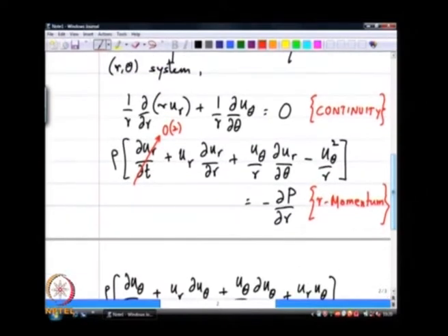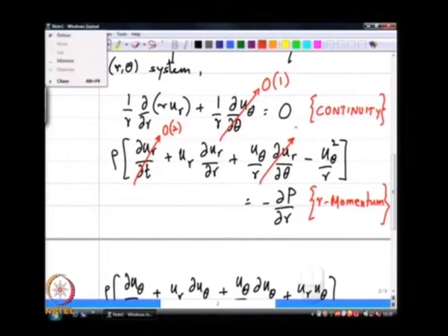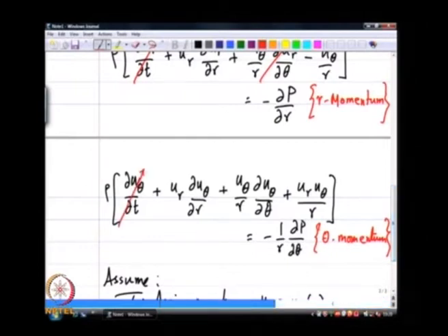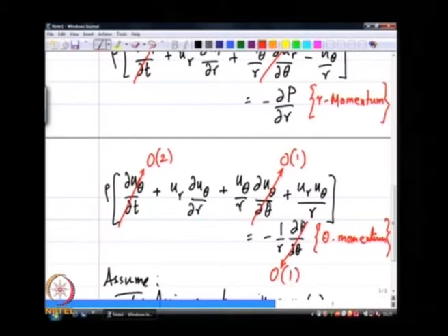Okay. So, if I now go through and scratch out terms and put in parentheses why that term is being scratched out, I will start with the first one. This is scratched out because of axis symmetry, this is scratched out because of the transient nature not being present. Again, this is due to axis symmetry. This is due to the transient nature not being present. This is due to axis symmetry. As well, this is due to axis symmetry.